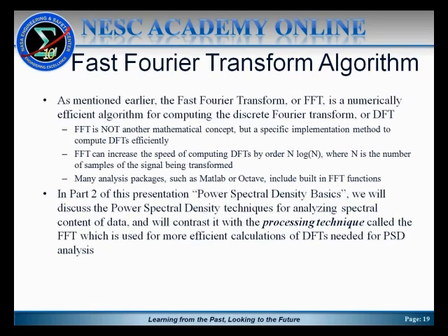And as I also mentioned earlier, it can dramatically increase the speed of computing the DFTs to the order of n times the natural log of n, where n is the number of samples that you're processing or for which you're computing the DFT. And as n gets very large, which it typically is for the signals we look at, that increase in efficiency can be very significant. And most analysis packages such as MATLAB or Octave already have built-in FFT functions as well, so it's easy to make use of what they've done.